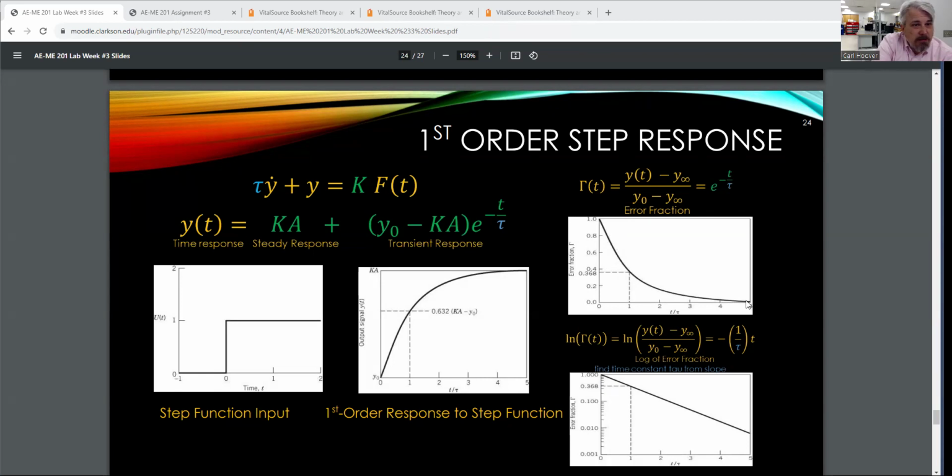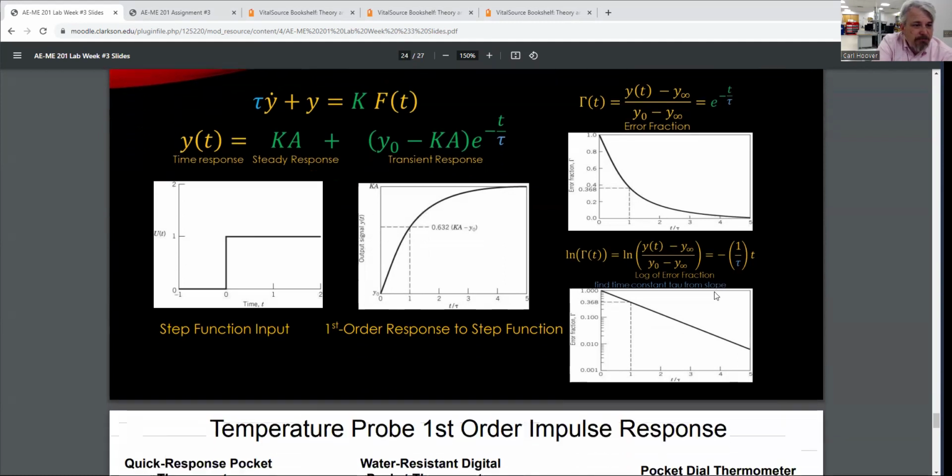A temperature instrument that responds very quickly will immediately draw down to the zero axis here and then go over. That'll have a lower time constant. Something that takes its time, perhaps like a bulb thermometer, will have a longer response. Depending on the use case, that really matters. Oftentimes we can take some time to measure something and wait. Other times we really need an instantaneous response. And typically the response characteristics are set in the specifications of an instrument.